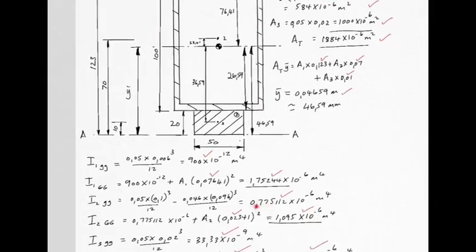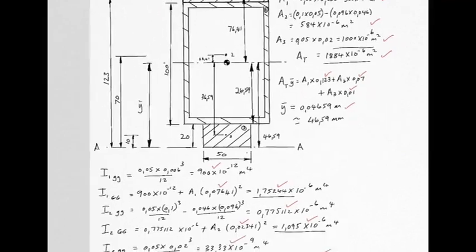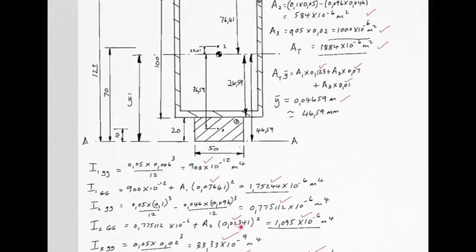But now, unfortunately, that's not the axis where you want it. You've got to find how far it is from 2's own axis to the actual axis where you want it. And once again, using arithmetic, make sure you agree with 23.41 millimeters, which is the dimension you're going to use in the parallel axis theorem: original answer plus area times distance squared between the original axis and the new desired axis. So there's your new answer.